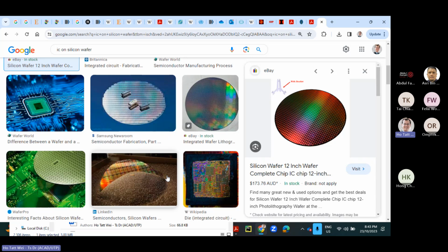Why am I saying that? Because when you use this Fourier transform, you know from Fourier transform, sharp edges are not very well defined. Maybe somewhere in the middle is okay, but towards the edges it gets a bit fuzzy. It's not very sharp when you create this type of edges on devices. So you can expect the quality of the lines, the features, or the geometries that you're trying to build on the IC at the edge is not as consistent as somewhere in the middle.